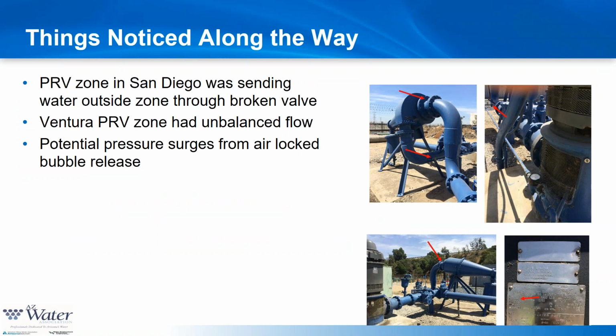This was validated by cloudy water downstream of this system and a lot of pressure transients. So what happens is that the pipe airlocked, and the air bubble went through the system and caused a water hammer that would then exacerbate the pressure on the pipe and break it. In the meantime, it would also airlock the pipe and hydraulically choke it, so the well pump was operating harder than it needed to. We said, let's put some air release valves in there.